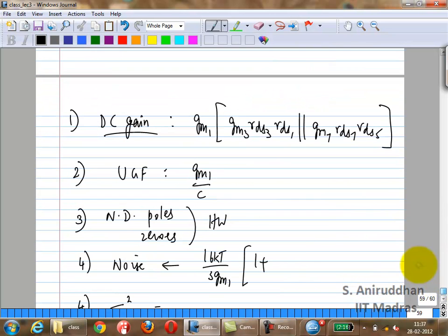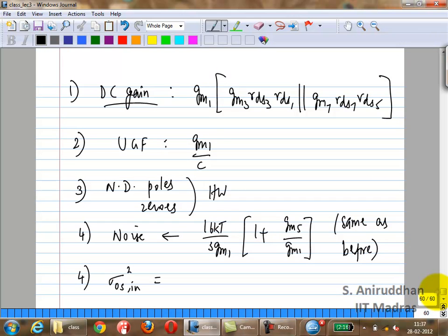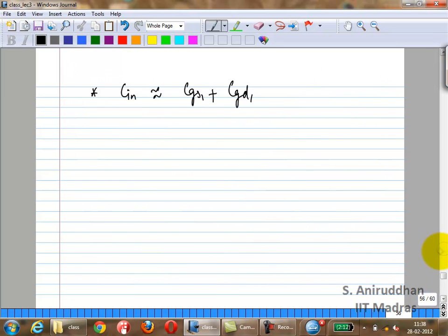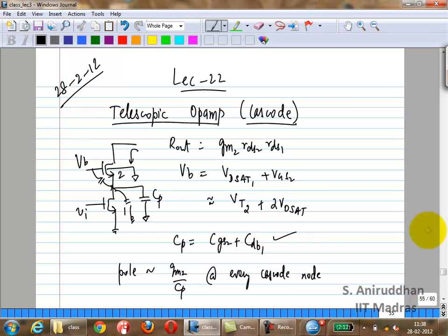In this case, I'll call it GM5. Okay? But now, there is one caveat, which is the same parasitic capacitance we talked about. If this parasitic capacitance is large enough, then it's going to be a function of frequency, right? Because the cascode gain of the cascode noise to the output is significant, right? Just remember that we actually worked it out in class, the dependence on capacitance. Okay?